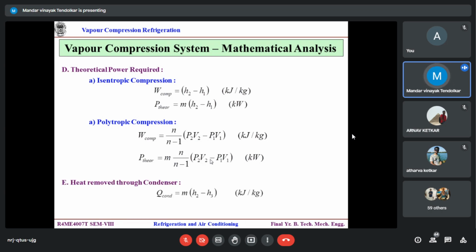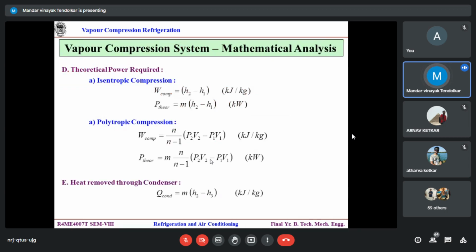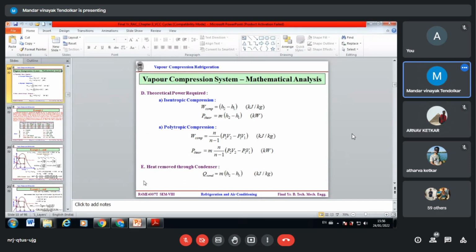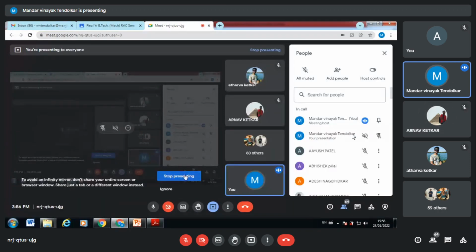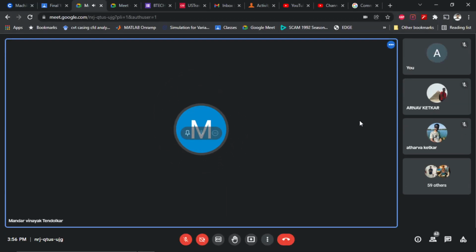So this is my mass just now calculated, multiplied by Vg at the inlet, because it is the compressor inlet. Right. Then power developed: same, m dot into delta H. Delta H is kJ per kg, m dot is kg per second, so it will be kilowatt. If it is a polytropic compression, I have to go with P2 V2 minus P1 V1, whatever that is, so that becomes a difficult task for us, times n upon n minus 1. Fine, it is a gaseous part, not such a big problem, but a difficult one.